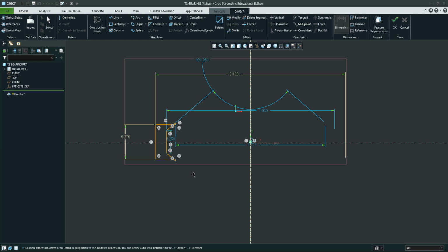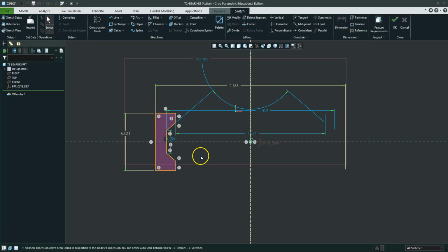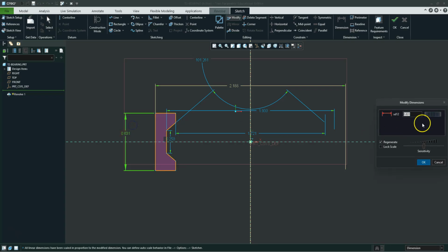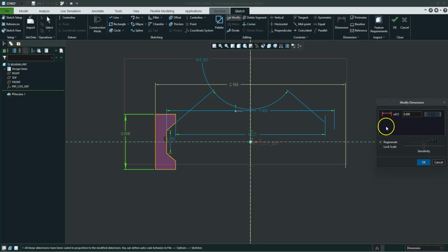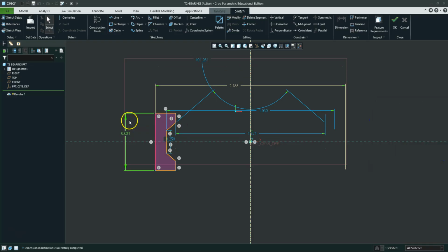We're going to see if that makes our sketch kind of weird. I thought it might, so if it does, that's okay. Let's just hit undo up here, or you can hit Control Z. All right, and we'll put some other dimensions in first that are going to control the shape of this, so that when this shrinks down the way that we just saw, it doesn't collapse on itself like that, where all of a sudden it's a little bit tougher to see what we were intending to do. Okay, so we'll just leave that dimension there. That's all good. And then we'll bring our dimension feature back up by clicking that.